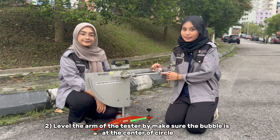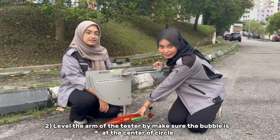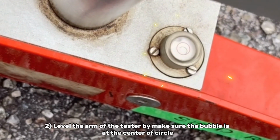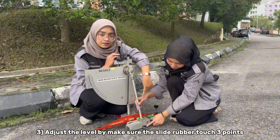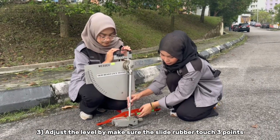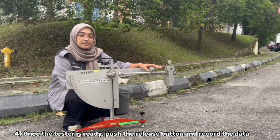To level the tester, we need to ensure that the bubble is inside the circle. Adjust the lever to ensure that the rubber of the skid tester touches these 3 points. Now we need to do 3 readings to get the average data.